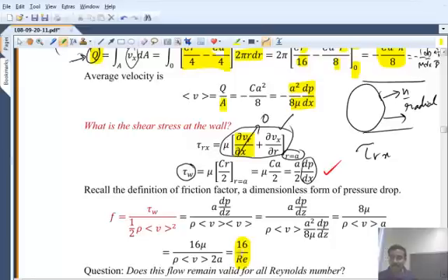And that result pops right out of this because the definition for friction factor is the shear stress divided by 1/2 rho V squared. That is a non-dimensional quantity that we define through that equation. You cannot ask why I defined that. You can define it in any other way you want. You will get a different number. Okay, but this is a standard definition that we accept. So it is shear stress divided by 1/2 rho V squared. V is the average velocity there.